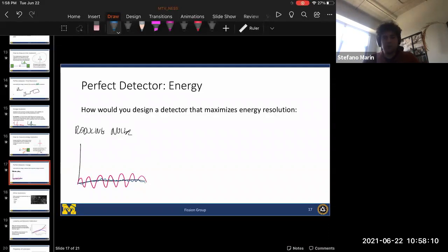Now, this, of course, is ideal, but how do we actually reduce noise in a detector? Well, we first have to understand what noise is coming from. Noise is basically random interactions or random things that can happen maybe down the line in your detector system, like in your readout, or it can happen at the detector itself, where simply randomly certain interactions are going to create a small signal. And all these interactions, over time, build up to a certain background pattern. This is usually created by some real physical events, and most of the time, this is a thermal type of noise.